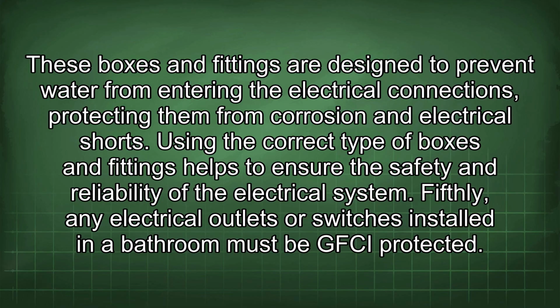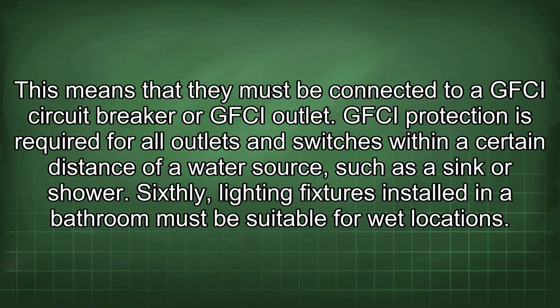Fifthly, any electrical outlets or switches installed in a bathroom must be GFCI protected. This means that they must be connected to a GFCI circuit breaker or GFCI outlet. GFCI protection is required for all outlets and switches within a certain distance of a water source, such as a sink or shower. Sixthly, lighting fixtures installed in a bathroom must be suitable for wet locations.